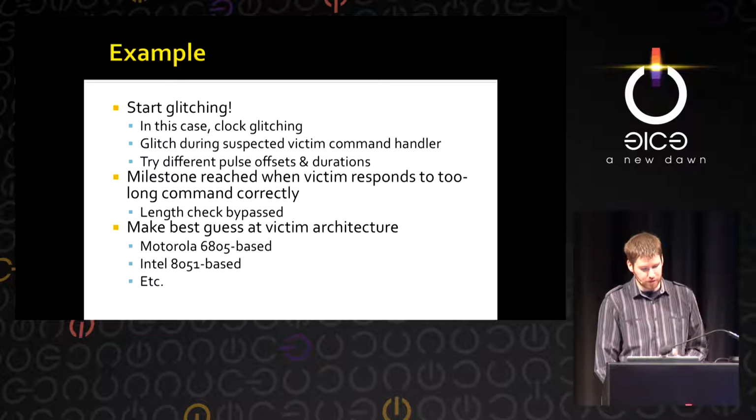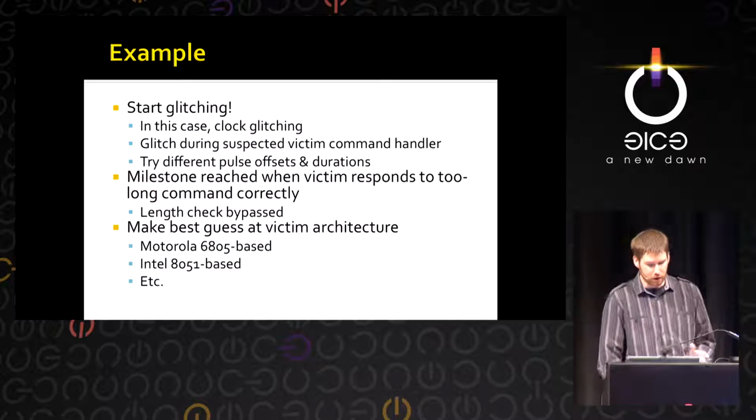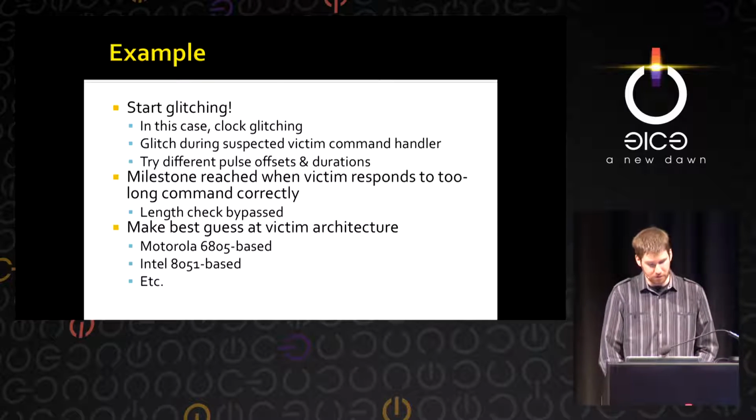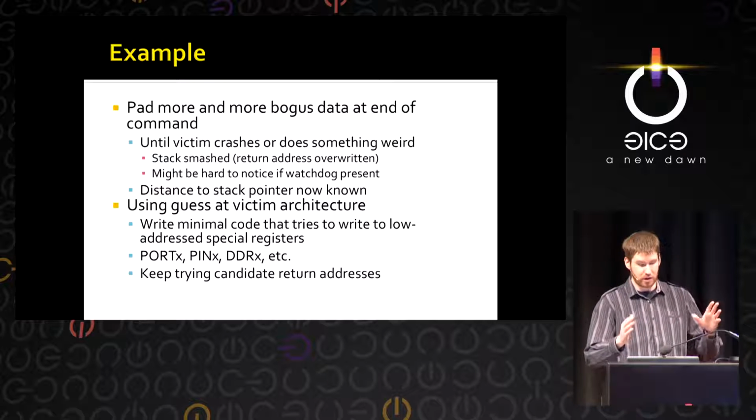At this point, there are usually Motorola 6805 based cores or Intel 8051 cores in the majority of smaller 8 or 16-bit embedded devices, so use that as your guess. As I said, you pad more and more data to the end of the command, and then wait till the victim crashes or does something weird. As you're padding more and more data, eventually it crashes. So now you've sent in a too-long value, but you make it even longer.